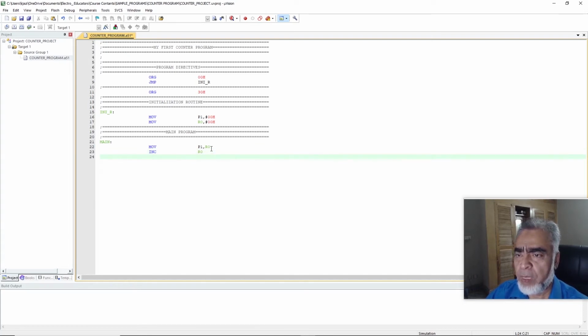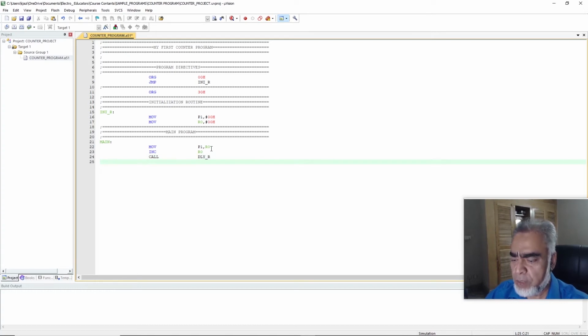Okay. And here we will call a delay routine, and we'll write call DLY_R. It means that we would like to call a delay routine to see the value on port 1, and now we'll write jump to main,